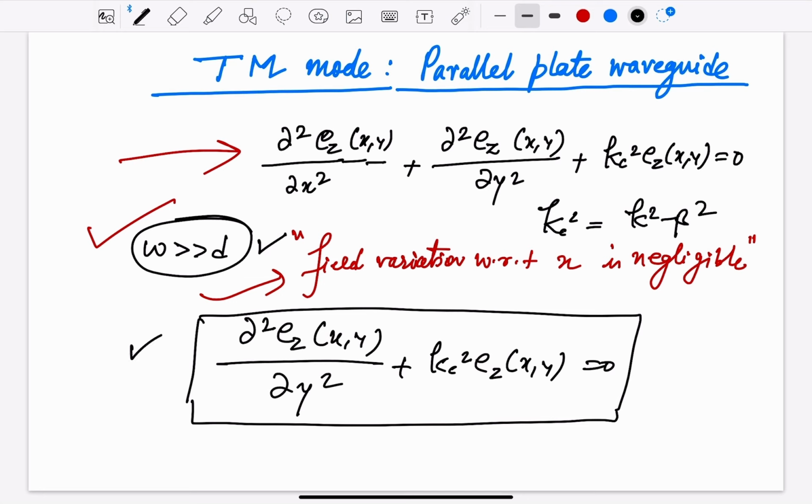Fine. So now let us define here once again the wave impedance for the TM mode. Recalling those relations, remember this was eta_TM is minus EY over HX. We already have this EY and HX, and these are the non-zero quantities here, and it would give you some expressions.